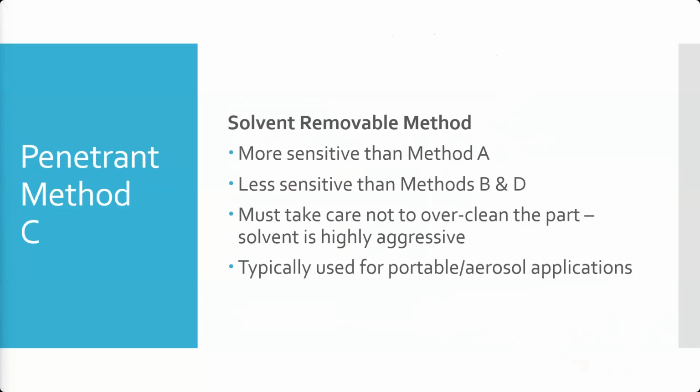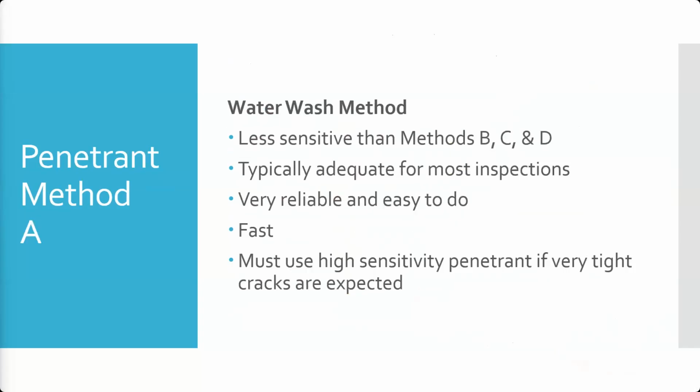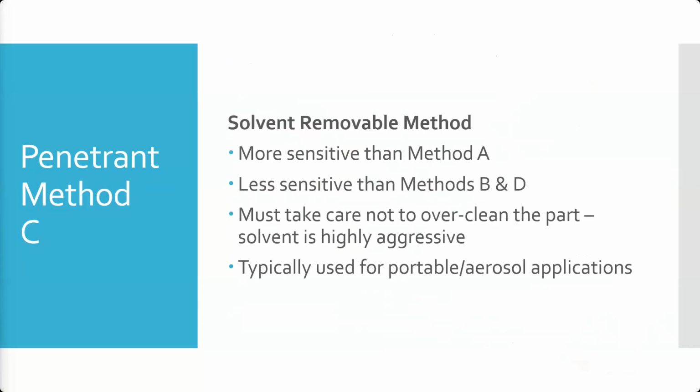In this case, because we're using a solvent and our penetrant is oil-based, we have to be careful that we don't overclean the part, because the solvent we use to remove the excess penetrant can also have the effect of dissolving the penetrant out of the cracks and crevices. It's highly aggressive, so we have to be careful and pay attention to how we're doing it. So it's a little bit more process dependent than your method A water washable, which is going to be the most forgiving.